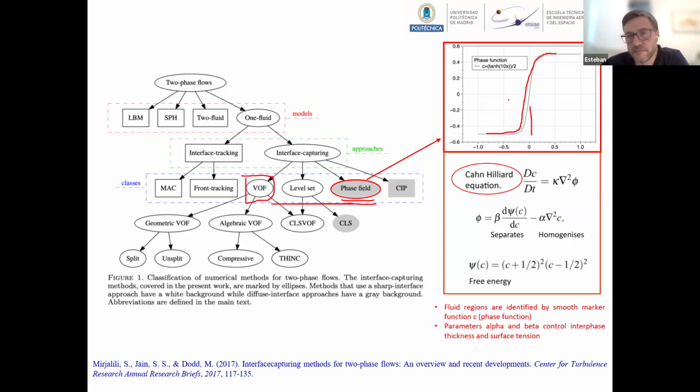We have a diffuse interface, a smooth interface, and hence we can do polynomial adaptation or any kind of higher order tricks without losing exponential convergence, without losing the nice properties of our higher order methods, right? So if we want to do this for multi-phase, we solve the Navier-Stokes equations, and in addition, we solve the Cahn-Hilliard equation, which governs the fluid concentration, right? So we need to solve these additional equations. Maybe not easy to solve, but it's feasible.